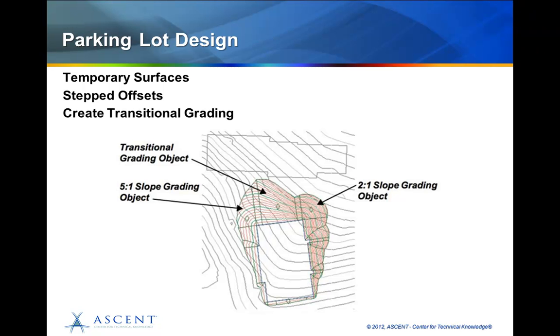going towards another right-of-way. And the reason that we do that is because the building is going to have a walkout to the parking lot at the second level, and then on the other side it just walks out to the existing ground. And so we build that parking lot up so that we have that option. And we do it with a retaining wall. So around the retaining wall we do have a 0.1-to-1 slope, and then on the other side I believe it's a 3-to-1 slope. So let's actually take a look at that.